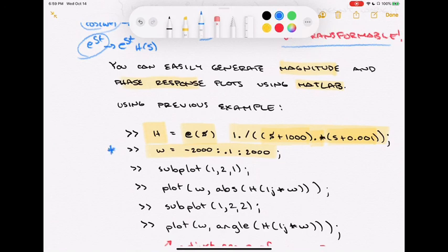You're probably going to have to adjust those frequencies to cover a range that hits the important detail of the system. So I would recommend doing this in an M file and then playing with some different values. If you make it a bunch bigger and you aren't seeing anything else going on, drag it back a little bit so you can focus on the area where action is happening. If you make it bigger and you see all sorts of new detail, keep making it bigger until you can see everything that you need to see.